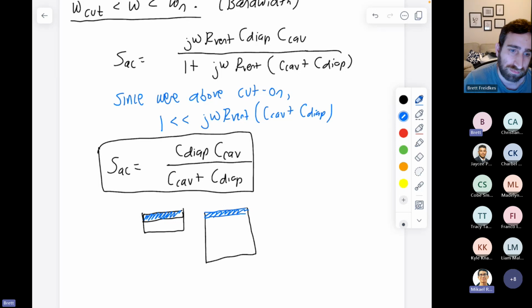Because as it squeezes, the pressure will increase a lot faster than the one on the right. Yeah, it's harder to compress the left one. There's not really any space for the volume to go. If you're assuming that both of them are at the same initial pressure, it is going to be harder to compress the left one. So we see that the cavity itself has its own stiffness associated with it, along with the general dimensions of the diaphragm. If you have this trampoline that is much smaller compared to much bigger, both of those things end up impacting the overall sensitivity of the device.